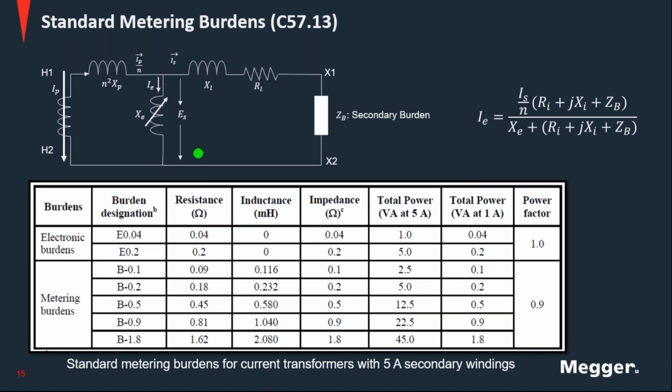This is the CT, and we can have the same thing for a voltage transformer, which will produce a voltage or a current at these terminals. Now this burden cannot exceed certain limits, because if not, it is not going to perform as specified. That's what we also have from the standard. We need to guarantee that the burden connected to this instrument transformer is not exceeding these limits.